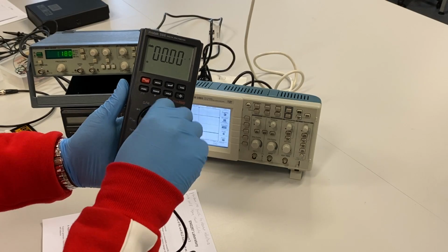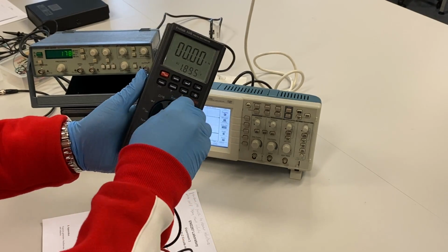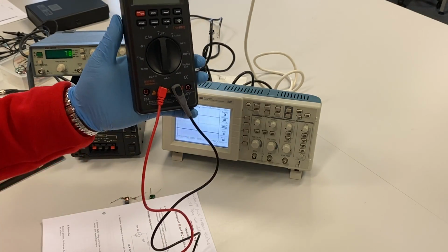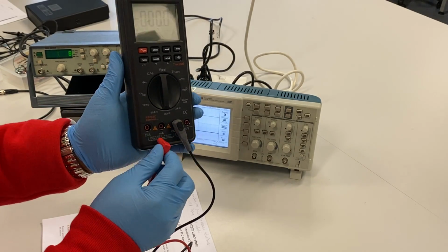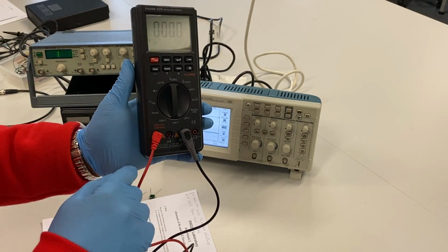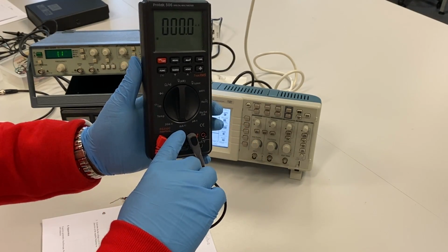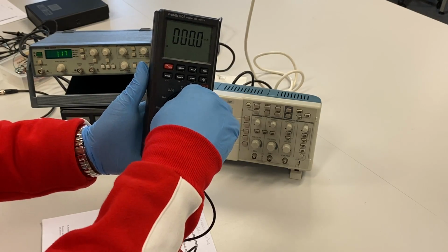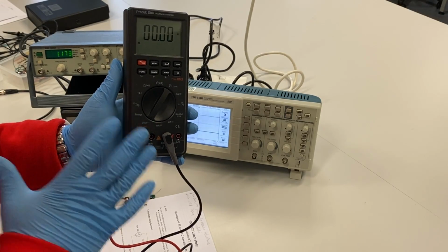So if you want to measure current, you just put it in milliamps, and what you do next is that you just turn this knob, clockwise or anti-clockwise. You just put it on 20 on milliamps. Once it's on milliamps, it can now measure current. So only if you're measuring current, you put this one either on milliamps or on 20 amps. But you see, now it's beeping because I put it on 20 amps, but this knob is on milliamps. So for it to measure under 20 amps, you just move this here, then it switches off. So this is for measuring current.